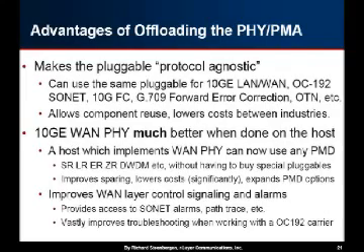So when I was talking earlier about whether the PHY framer was on the pluggable or not, this is what I mean. Basically, there's a big advantage if you take the framer, the physical layer framer, off of the pluggable itself, and that lets you make the pluggable protocol agnostic. So you now have the same pluggable that you can use for 10 gig LAN or WAN PHY. You can use it in OC192. You can use it in 10 gig Fibre Channel,